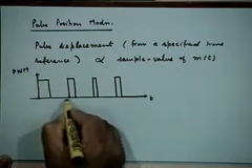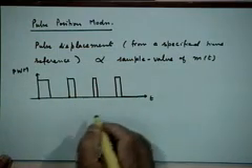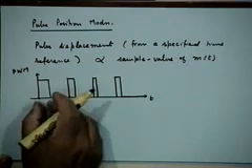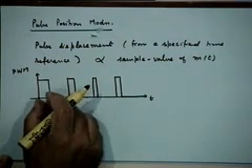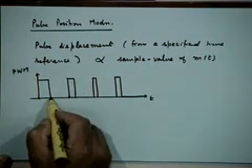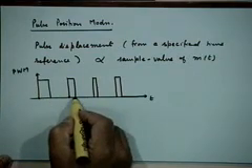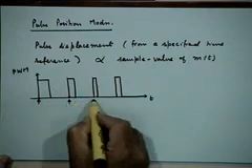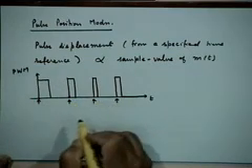This time interval is 1/Fs, which is fixed. Now you want to generate a pulse. Remember, this width is proportional to the amplitude of the message. So basically, where do you want to produce your pulse? At this point. Here the reference point is this. So the time reference points are these.